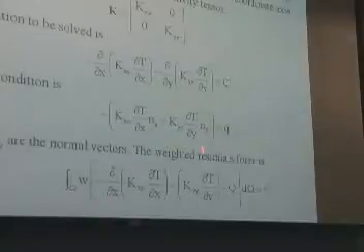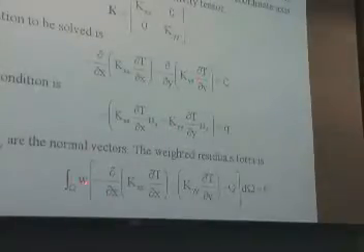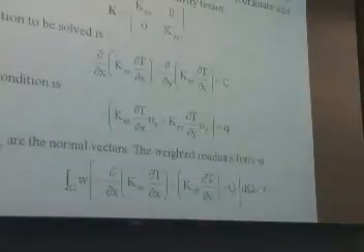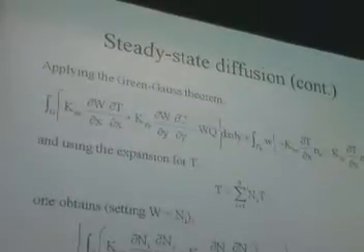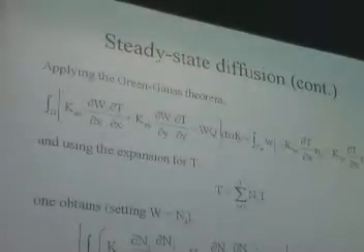Here's the governing equation right here. I multiply by a weight and I integrate, set it equal to 0. That's the method of weighted residuals. That's all it takes. This is what I wind up with. Now, in 1D, it's called integration by parts. When you go to 2 or 3 dimensions, it's called Green-Gauss theorem. So if you want to impress your people over in the math department or somewhere else, just tell them that you had a lecture on application of the Green-Gauss theorem today. It's really integration by parts in 2 or 3 dimensions.